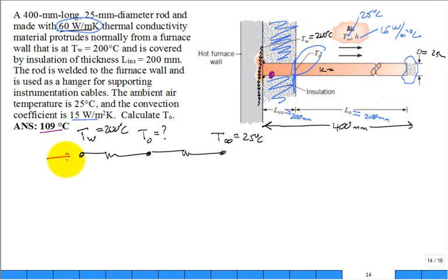And what do we have flowing through it? Well, I don't know the rate of heat transfer through those resistors. But it flows straight through this part, and then it's going to be convected off of the protruding rod and into the fluid. Okay, so this resistance is the easy part. L divided by KA. It's just one-dimensional through a rod.